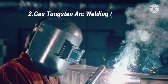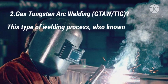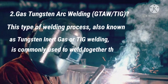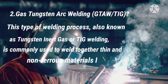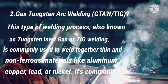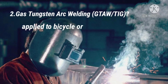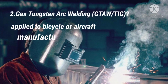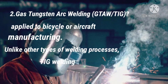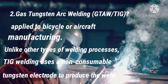Gas tungsten arc welding, GTAW, TIG. This type of welding process, also known as tungsten inert gas or TIG welding, is commonly used to weld together thin and non-ferrous materials like aluminum, copper, lead, or nickel. It's commonly applied to bicycle or aircraft manufacturing. Unlike other types of welding processes, TIG welding uses a non-consumable tungsten electrode to produce the weld.